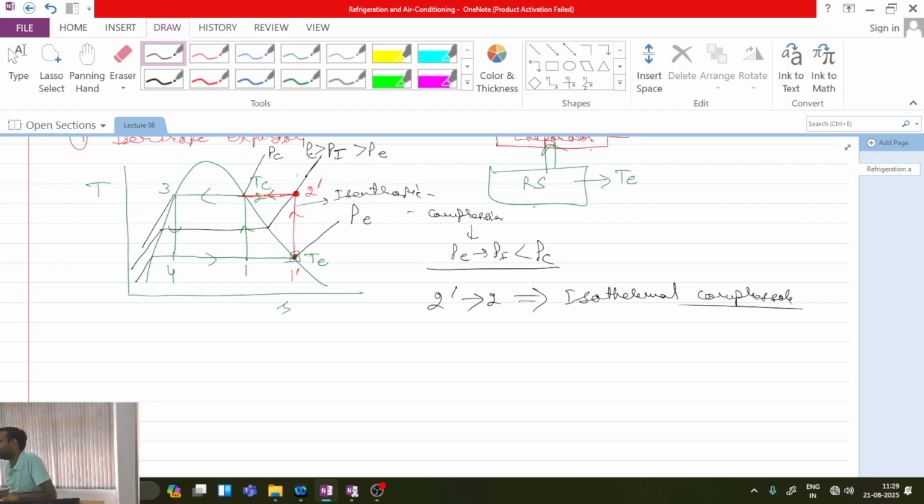Temperature increases. But if you slowly move the piston, does the temperature of air increase? It doesn't increase because of the compression process; whatever slight increase in temperature is there, you have allowed a finite amount of time for the gas to dissipate that heat to the surroundings. So you are doing compression in a quasi-static fashion.